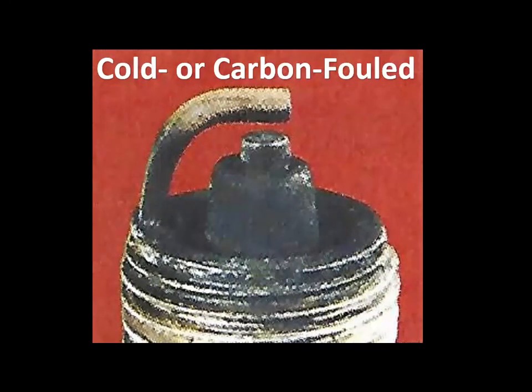Other causes include secondary ignition misfiring in the spark plug, a colder than specified spark plug heat range, or low cylinder compression.